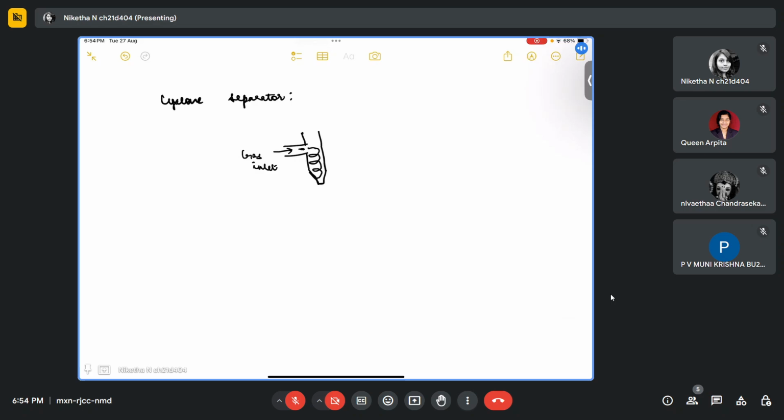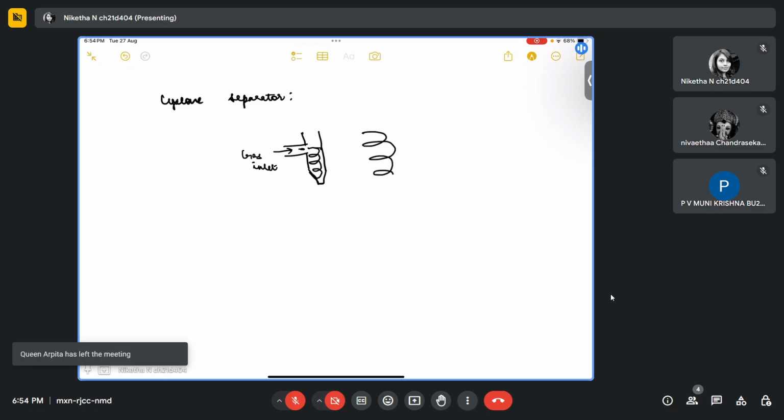Why this vortex happens is because centrifugal force will make them hit the surface of the container, whereas gravity will tend to make it move downwards, and therefore there will be a vortex type of motion. So when the particles present in the vortex hit the wall of the cyclone separator, immediately they'll be out of the vortex and they'll slide down and they'll be collected at the bottom.